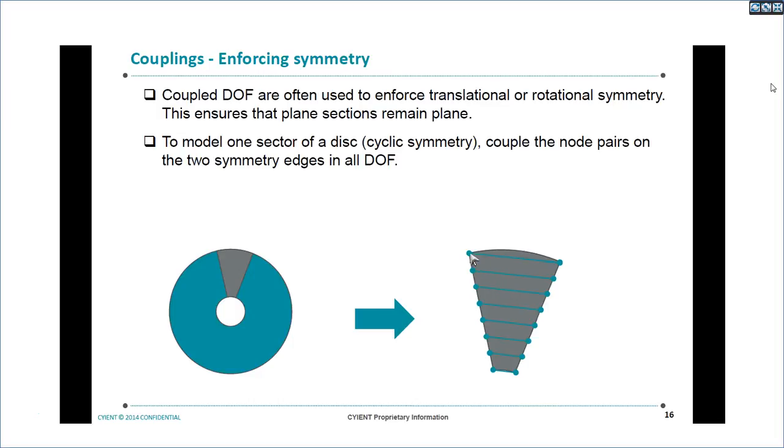So here, we can put the nodal couplings on the two symmetry edges in all degrees of freedom. So what we'll do generally is take the cut faces, match the mesh pattern at the cut faces, and couple these cut face nodes. So that will enforce the symmetry.